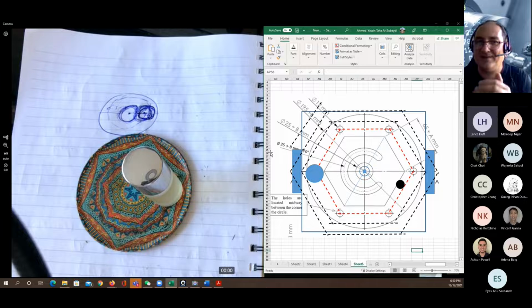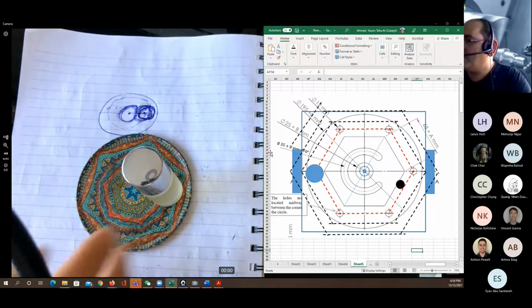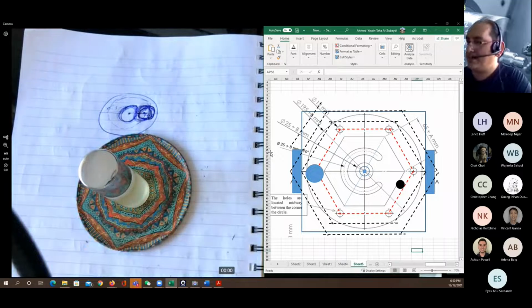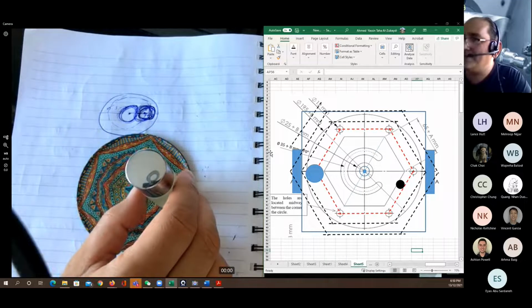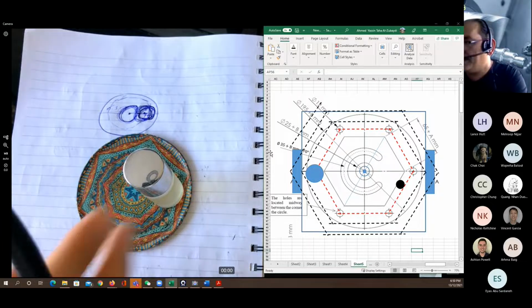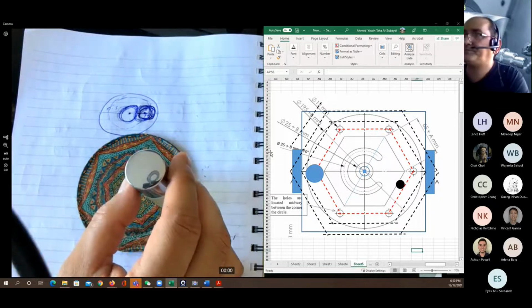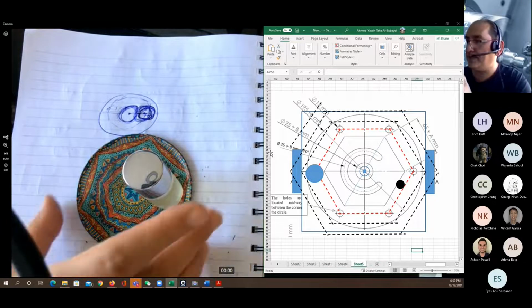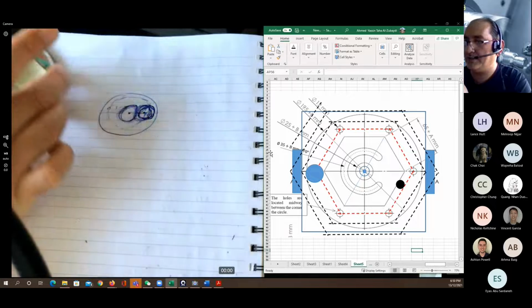Yeah, thank you. Great. Okay, so now that means this one was a 0, 0, of course. When I'm going to push it to the side, I will say G01, the Y is going to be 0, but the X is going to be equal to 6.5. Then I'm going to make a full circle. Now we have a problem here.